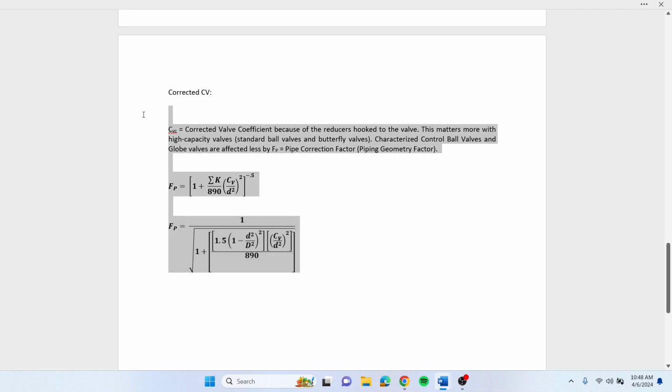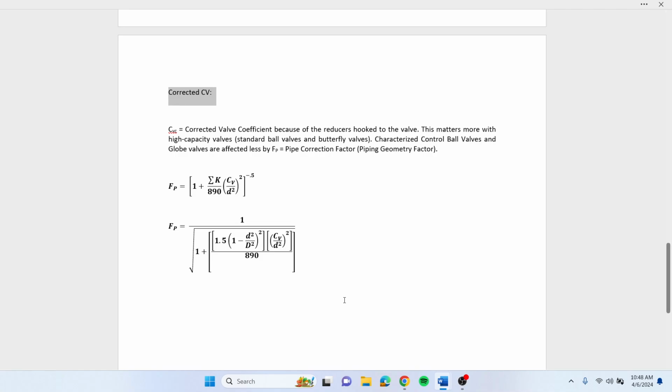We'll go over this in another video, but I just wanted you to be aware that you might hear about corrected CV. The other thing you might hear about is choke flow. On a standard coil with a 3 to 5 psi drop, I'm not worried about it because it's more the case with steam. We'll go over this in another video again. With water, if you drop pressure too much, choke flow just means any more differential pressure across that valve isn't going to cause any more flow through the valve because they've reached that choke point. With water, what you've got to worry about is that you don't want the water to flash to steam, because then you have cavitation, which ruins valves, all that stuff. I'm not worried about it on a standard 3 to 5 psi drop though.